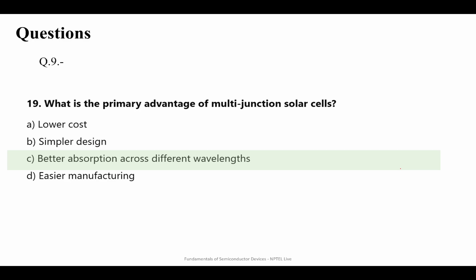Because you are growing another material on top of silicon, there will be defects created in that top material. Like last week we studied epitaxy, right? So there will be lattice mismatch effects and other epitaxial defects. All those issues are there for a heterojunction. You are basically creating a heterojunction there. Yes, sir, multi-junction is also called heterojunction. You are doing heteroepitaxy, so that will create issues.